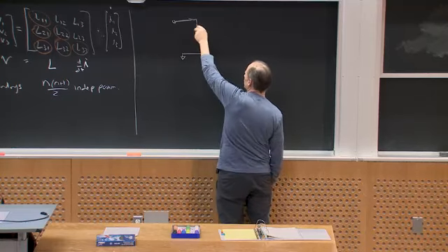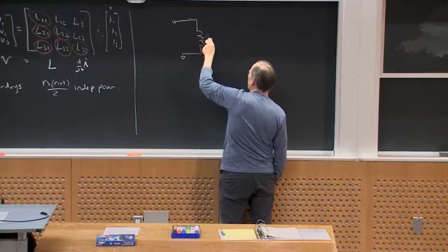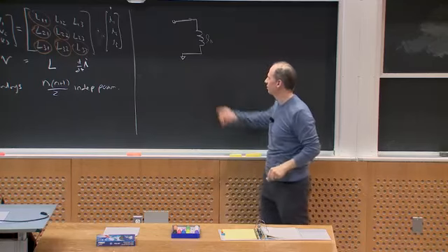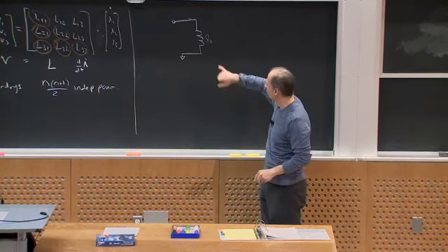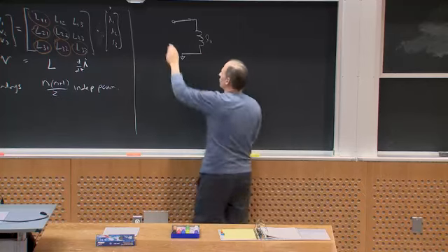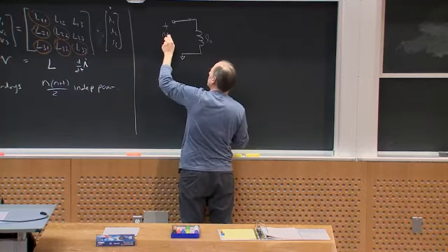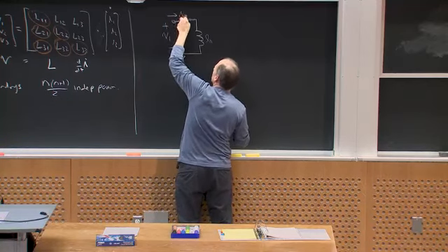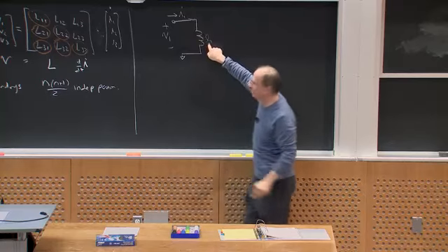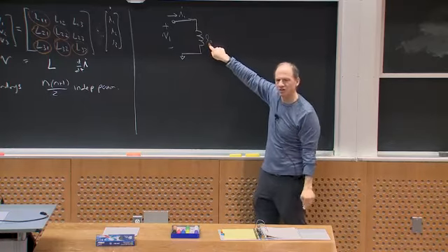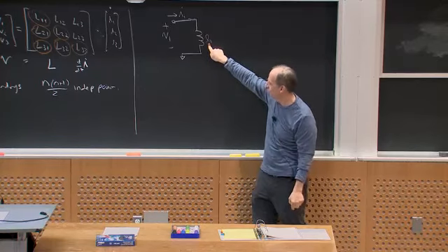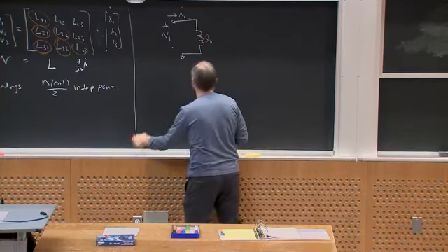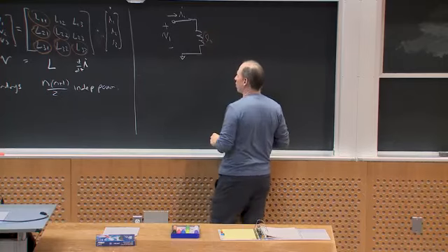This is my inductance L, but I'll call it L11, using little L11 to distinguish it from my inductance matrix value. If I just had a single device with V1 and I1, I'd need one parameter, little L11, which is just the inductance of that one winding. So I have one parameter here that captures what I want.